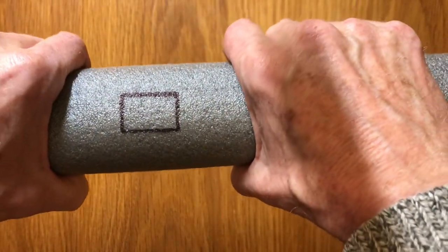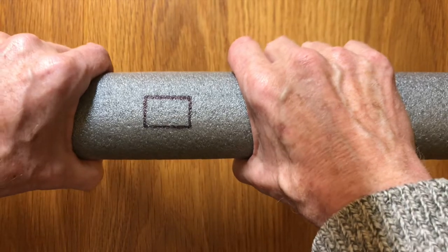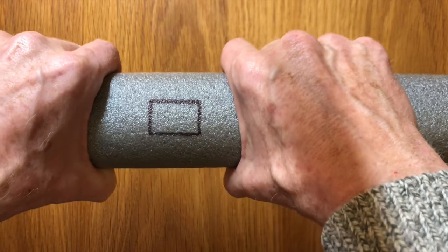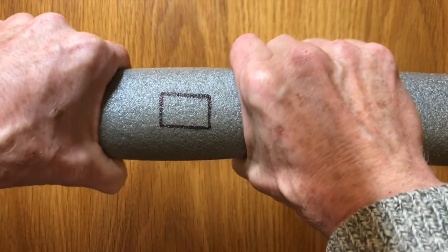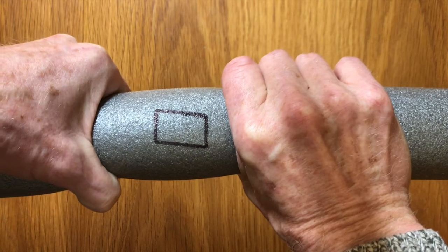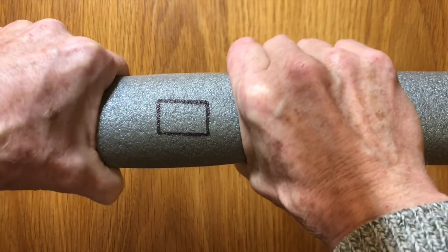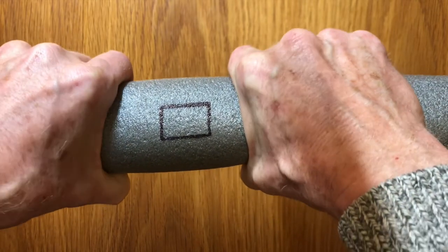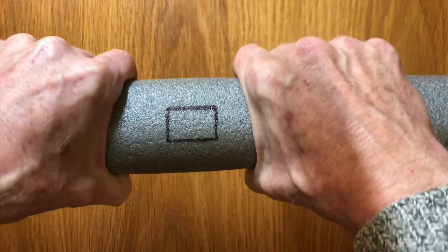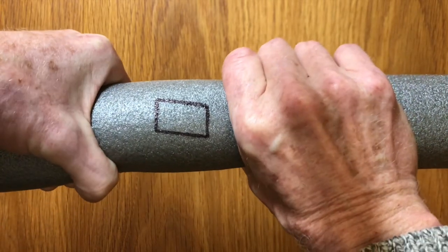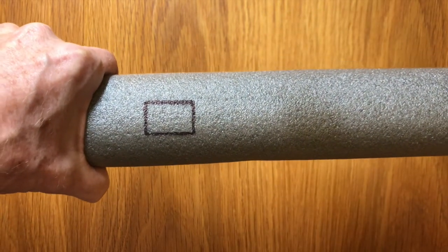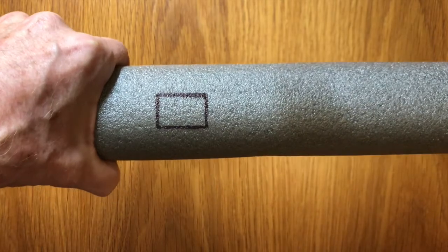Here we have an example of shear stress in action. You can see on this simulated steel shaft, I've drawn a rectangle there with nice 90-degree corners. If I twist it like this, you'll see that becomes a parallelogram because the shaft, when it's twisted, actually produces a shear stress on the surface of the shaft. If I go the other way, you can see it as well, quite clearly producing the parallelogram that you associate with shear. Normally, if you overstress a shaft like this, it will snap and fail in shear, and I'll give you an example of that.